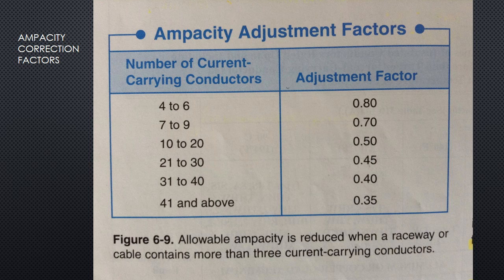When working with the correction factor for multiple conductors in a conduit, not all conductors are included in the count. Equipment grounding conductors and the neutral conductor in single-phase 3-wire circuits are not counted because they normally carry no current. Therefore, they generate no heat. Neutral conductors that regularly carry current are counted, however.